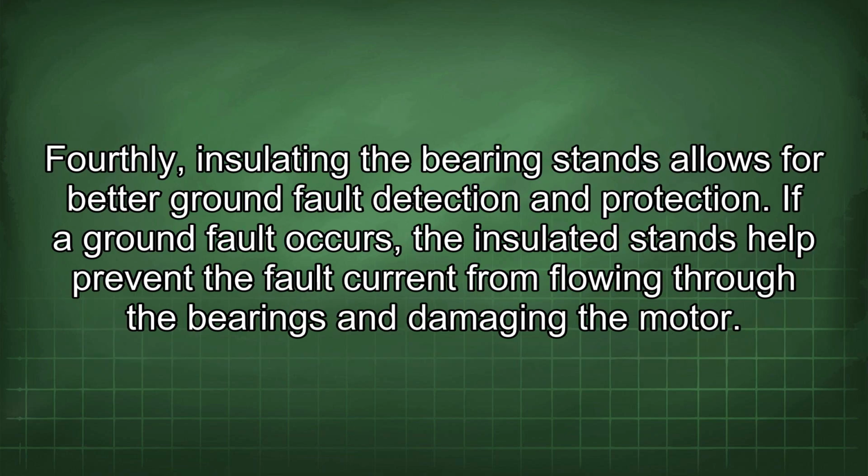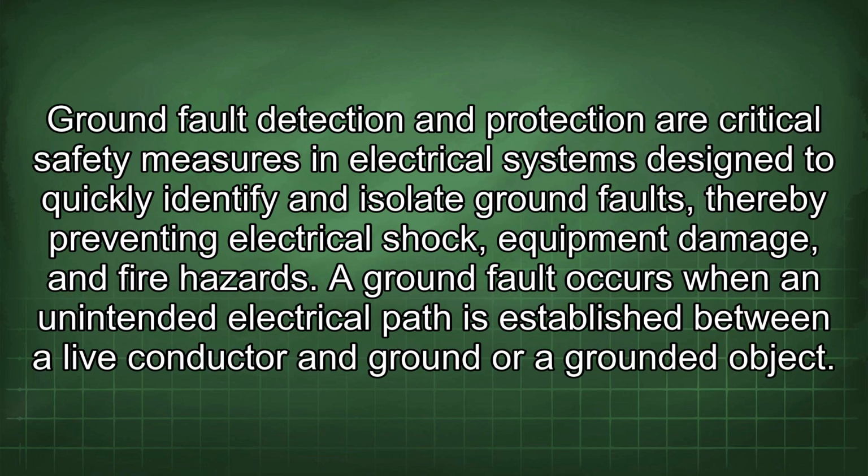Fourthly, insulating the bearing stands allows for better ground fault detection and protection. If a ground fault occurs, the insulated stands help prevent the fault current from flowing through the bearings and damaging the motor. Ground fault detection and protection are critical safety measures in electrical systems designed to quickly identify and isolate ground faults, thereby preventing electrical shock, equipment damage, and fire hazards.